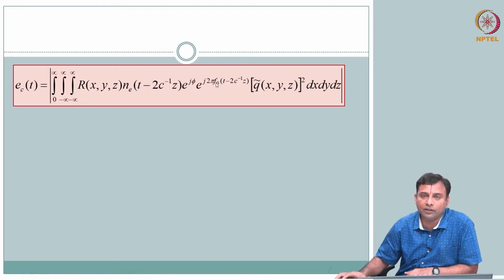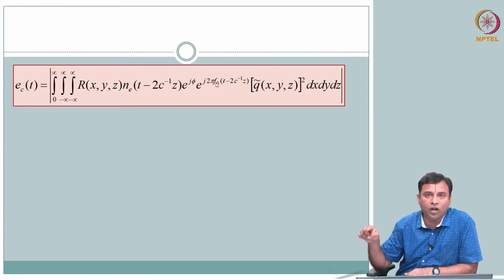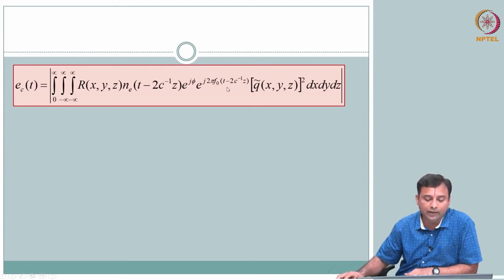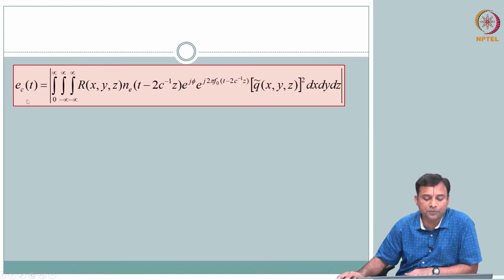Go back and look at the first part, just after the transducer, when we talked about sending a cosine pulse, some pulse for which we also plotted the envelope. That is the pulse that is sent in, a narrow band pulse. At that time we wrote n of t as n e of t, an envelope of the signal with the phase, and you had this f naught, which is your high frequency. So, this is just brute force substituting that, and this modulus gives you the envelope, because this is a complex signal.